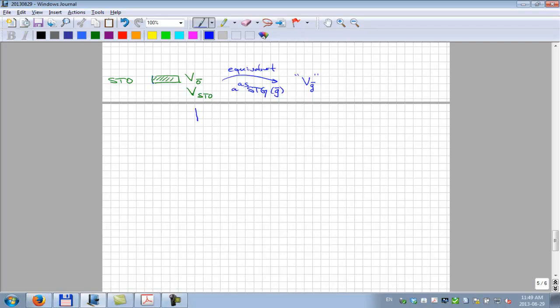Yeah, so what if we convert this volume into moles of stock tank oil? And then we just stamp it with that number, 23.68 or 379. Okay? So we've got to convert volume to moles, and then we multiply by this RTSC over PSC, which is what we've called that. So we basically want to multiply by that number there. But first we have to convert from volume to moles.